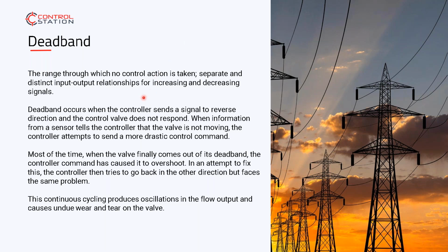typically is from a degree of valve lash, is what it used to be called. This looseness in the components. It's less and less prevalent in valve design now. A lot of that has been designed out of it as we've moved away from classically pneumatic and linkage controllers to more direct drive controllers, direct drive valves, etc. But it still exists. It's still in there in the process.